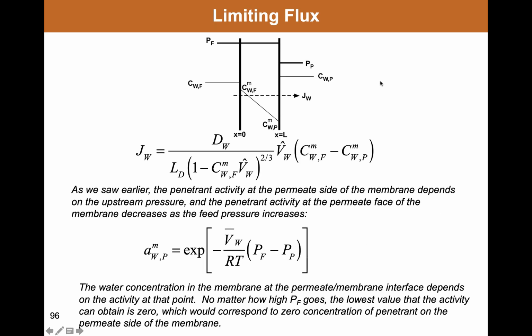There is a concept here of limiting flux that is interesting and comes up in liquid permeation, particularly in organic solvent permeation through polymers. So here's the expression for flux that we've worked very hard at deriving, in terms of the diffusion coefficient of solvent through the membrane.